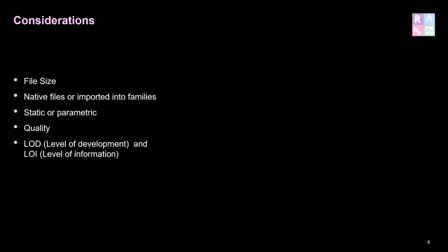And then you have to consider the LOD and the LOI, level of development, which really has to do with how detailed the model graphically looks, and LOI has to do with the information. Does it hold metadata about the warranty, the model number, the contact details, or does it just say Dell computer monitor, and that's it, nothing else? That's what LOI means. And then next is whether it's hosted or not. I'll get into that in a second.